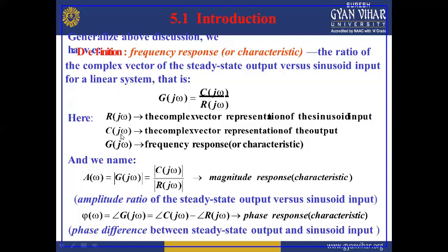That means from the frequency response, we can do the analysis differently for the magnitude as well as for the phase. In the frequency response, we will be having two graphs: one is the magnitude plot and another is the phase plot. So it's very easy to understand the behavior of the system in the frequency domain, to analyze the system with the magnitude and the phase part both separately and also simultaneously. The same concept has also been implemented using the Bode plot, which we will be discussing in the coming sections.